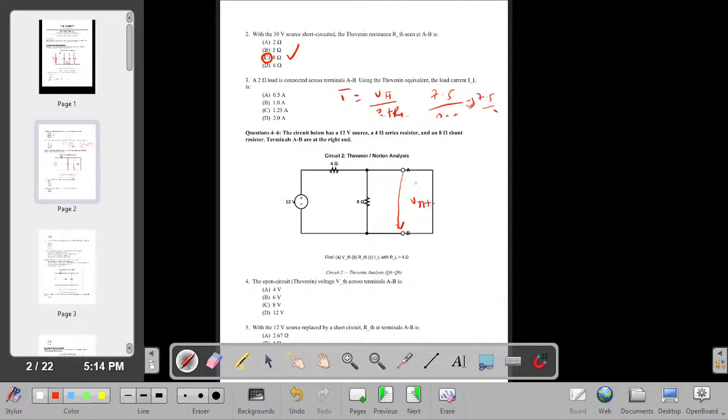Now, analyzing a circuit like this, this is a simple circuit. Don't worry yourself to go and find I1, I2 and all that. Please take note: the current produced by our source, labeled I, will pass through the 4 ohm. Upon reaching this junction, it has no other option except coming down. Once it comes down, it returns back to the source. It doesn't flow through because this is an open circuit. There is no chance for it to move.